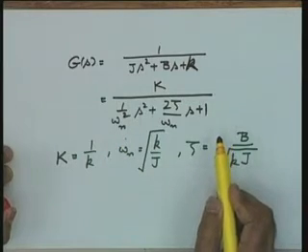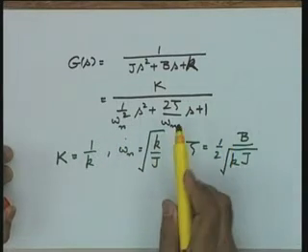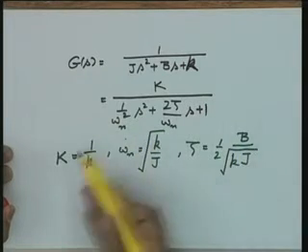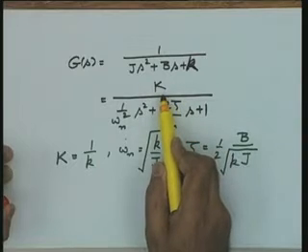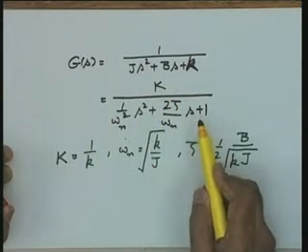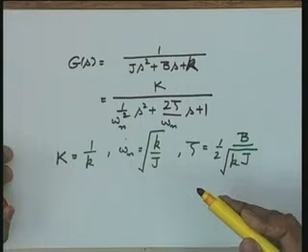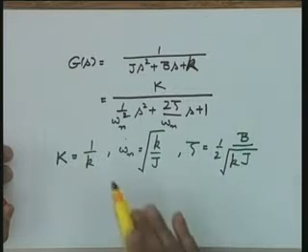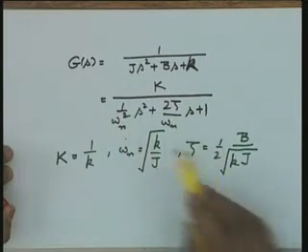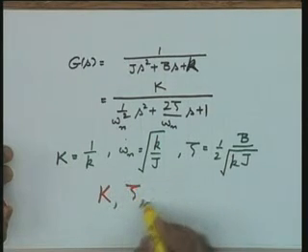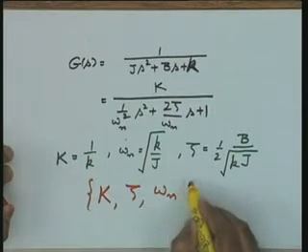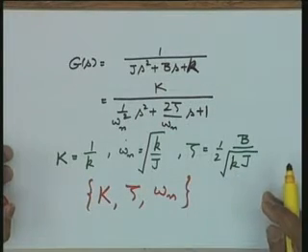The K has the same meaning. This you can check by the final value theorem as well. You see that for a step input, please help me, you can immediately check. For a unit step input, the final value of the response is given by K. Just immediately apply the final value theorem and check, please. So, it means this is the gain of the system. Okay. So, now I have to concentrate on the parameters zeta and omega n, because my claim is this, that K, zeta and omega n, these three parameters describe the personality of a second order system in general.